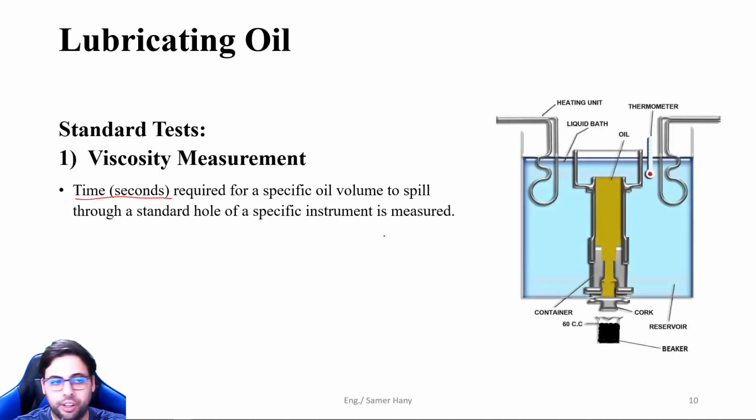Okay, so let's look at this instrument here. Here's the oil compartment. We fill this compartment with our sample of oil, and then this compartment is in a liquid bath. Typically, this is a water bath, to heat or keep the temperature of the test consistent, since we already know that the viscosity will change with changing temperature. And this is the standard hole that we talked about.